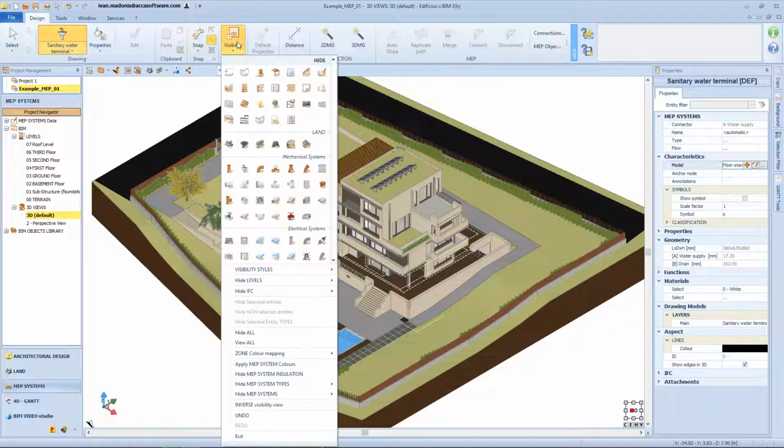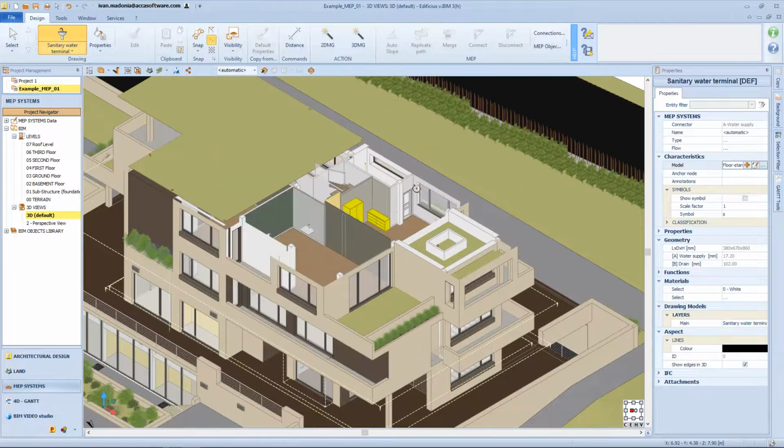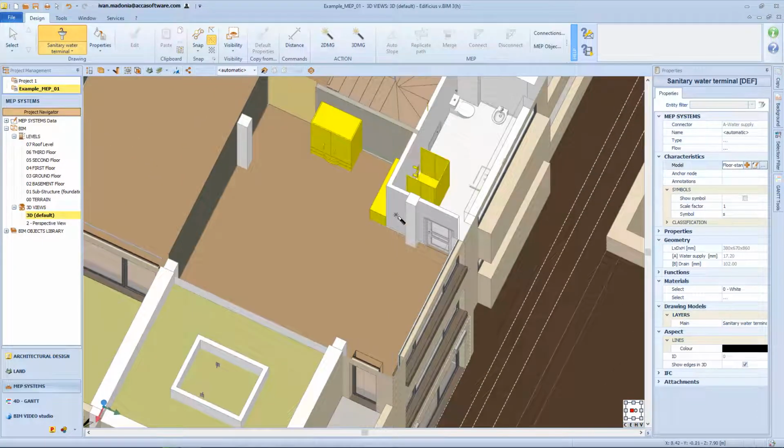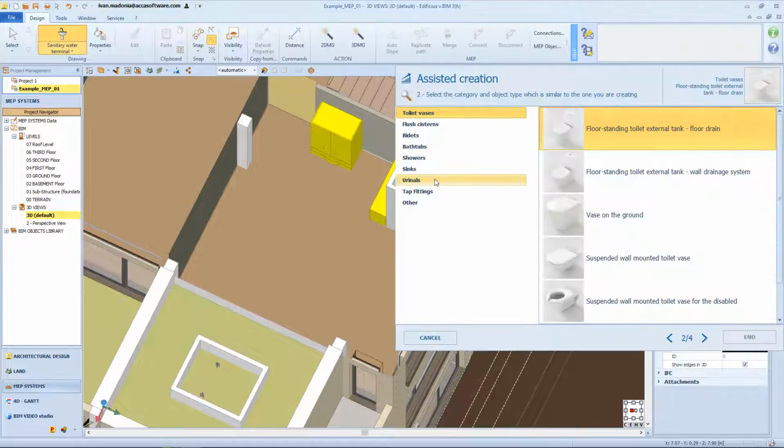We can then access the model view where you can recognize any 3D models available to be converted, as they appear colored in yellow. Moreover, passing over with the mouse cursor, you'll see that they will turn red instead, to specify compatibility with the conversion to be carried out. By clicking with the mouse on one of these blocks, in the specific case of the shower box, it's selected for conversion and the second step of the guided creation is now ready.